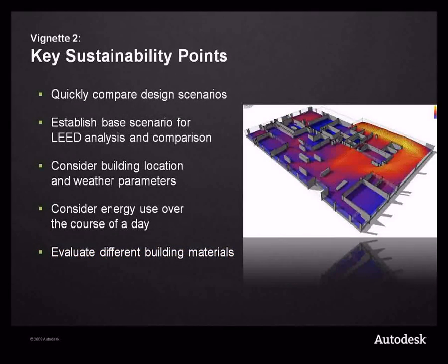While this vignette shows a very simple example, you can see the power of Revit MEP to quickly compare design scenarios. Revit MEP makes it easy to establish a base scenario for analysis and comparison. You also saw how Revit MEP considers building location and weather parameters for that location, and allows you to consider energy use over the course of a day and allows easy evaluation of different building materials.